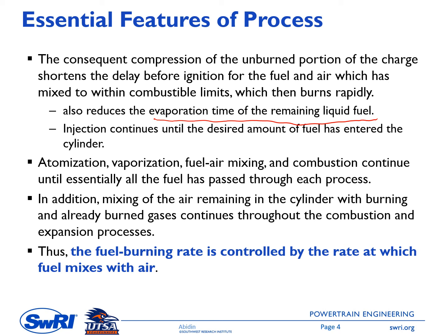So in this case, the atomization, vaporization, fuel-air mixing, and combustion continue until essentially all the fuel has passed through each process. And then in addition, mixing of the air remaining in the cylinder with burning gas or already burned gas continues throughout the combustion and expansion process.